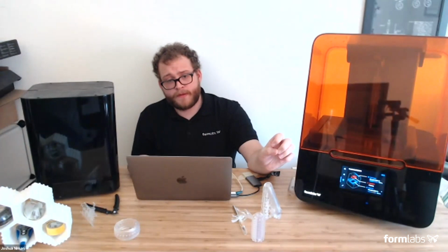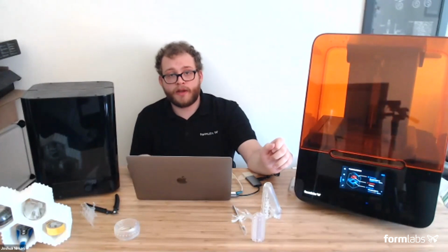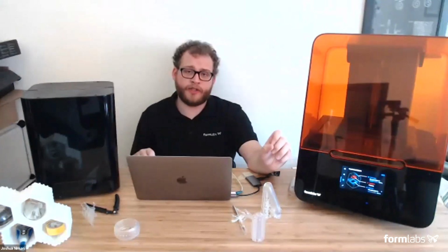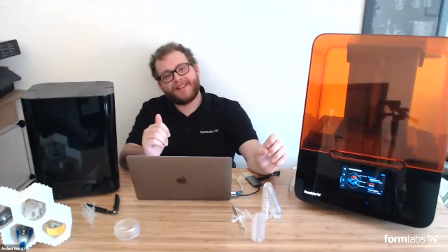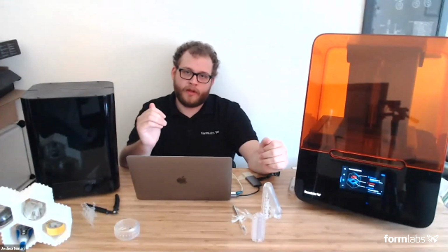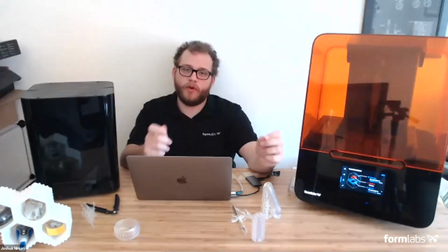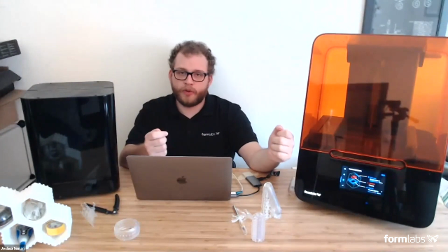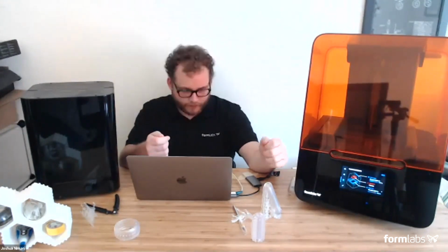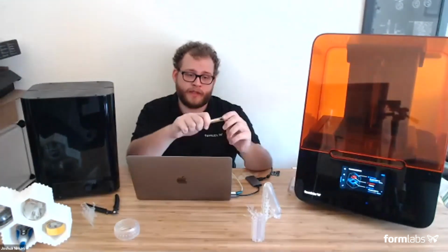Tying this to another one of our materials that you may or may not use, we actually came out with some really cool supports for castable wax not long ago, which are designed to never break away cleanly at the surface of the part. It sounds stupid, right? They break further down the body of the support so that you always have a positive entity that you can then remove, because it's a lot easier to remove more material than it is to fill it in. And removing that positive component, I like to use an X-Acto knife.